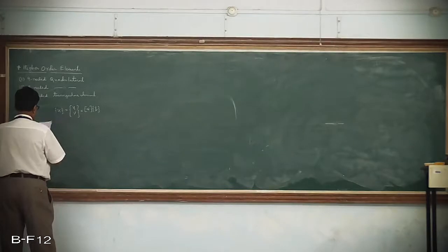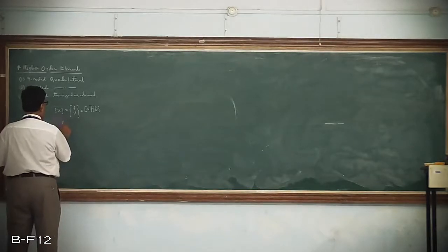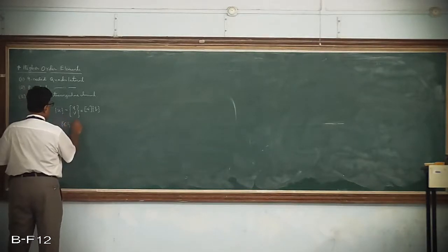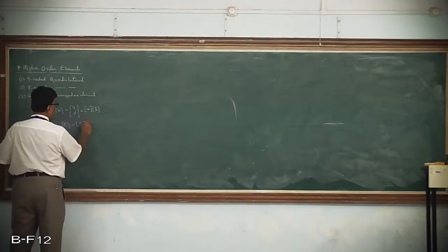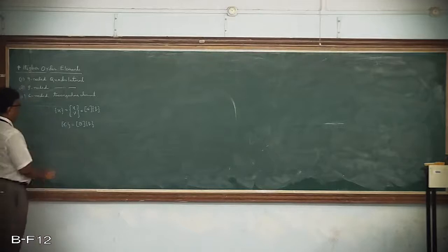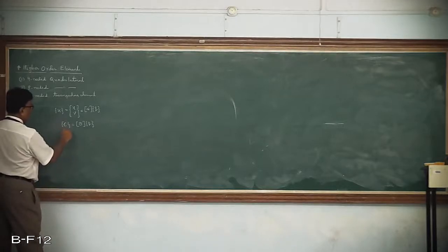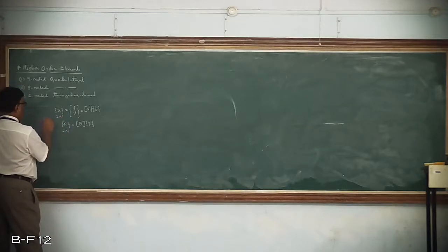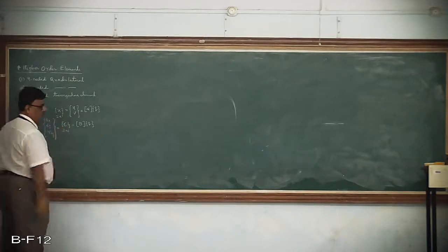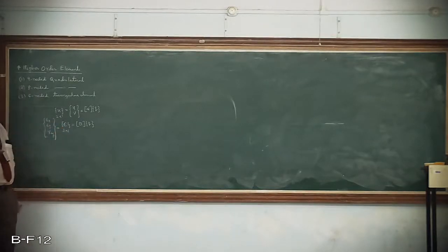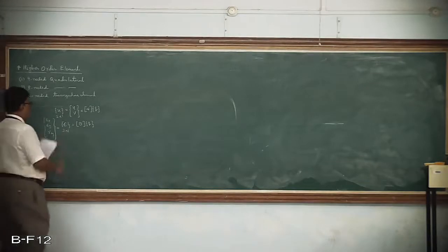So next, if you come across the strain, strain is again one and the same, but these B and Q, when you look at their sizes, depend upon this. Of course, you remember that these are going to be 3 by 1 only. This is again going to be epsilon x, epsilon y, and gamma xy only. For all 2D elements, these three components of stresses are always going to be given. So that is going to be given by this equation.